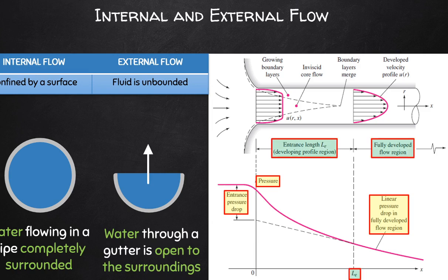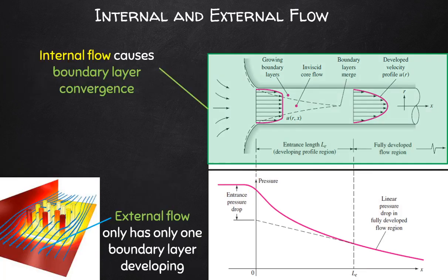Now, the entrance length is defined as that part of the pipe in which the flow is still developing, and the pressure drop is of course non-linear. And obviously we can't accurately determine the pressure drop using the Darcy-Weisbach equation alone, so we've been adding things like the resistance coefficient method, Kr, to account for the associated pressure drops when dealing with pipe entrances as well as pipe exits.